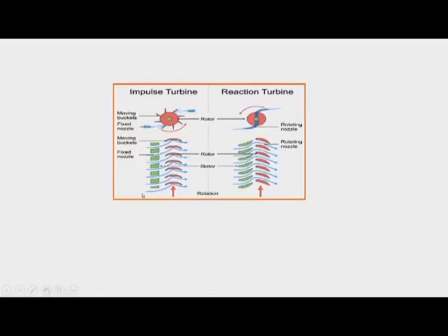In the case of the impulse turbine, fundamentally the motion is governed as we can see in the case of a water turbine, where a jet of water imparts force on the blades of the turbine and then the blade rotates. Here as well, the nozzle will generate a high kinetic energy flow and then the flow hits the turbine blades, due to which the turbine moves in the upward direction. In the figure, it would move in this direction toward us.